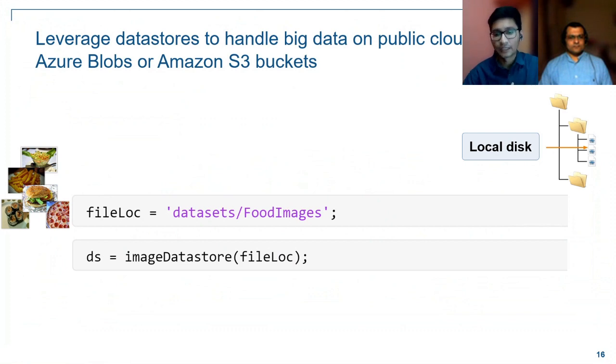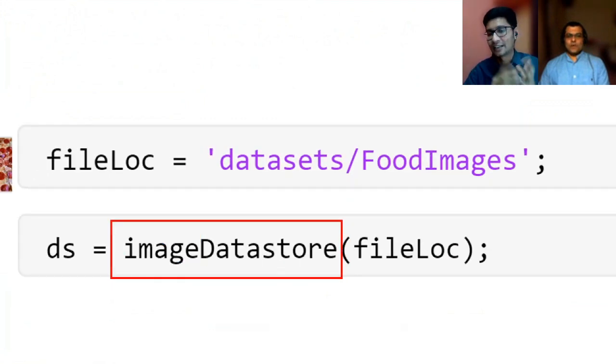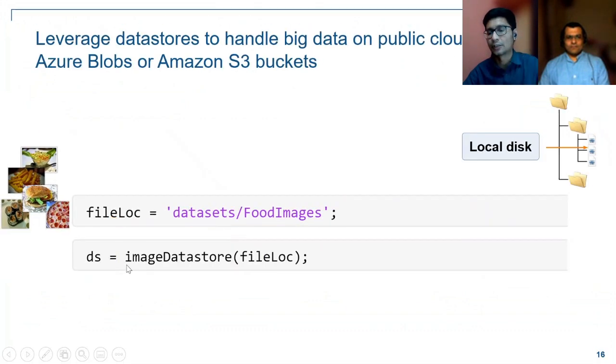You want to access the data, right? Yes, that's the first step. As you mentioned in the example, fleet data is residing on an S3 bucket or blob storage, so how do you pull the data into the MATLAB IDE? That's a very interesting question. What you see here is the program to pull the data from your local disk, and we have a datastore. A very interesting pointer to discuss. It points to the data, and you can easily create a pointer for the entire data, whatever you're trying to do. It can be big data, small data of a similar type. So to pull the data here, you just use the datastore and specify the location.